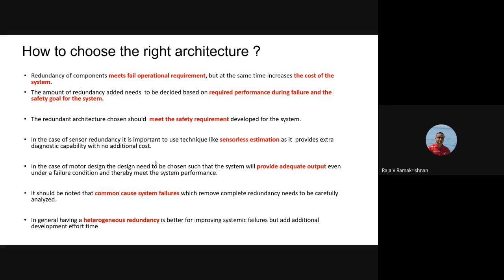You can have multiple windings there too, but you need to analyze such concepts and understand the common cause failure and bring down that FIT rate, making sure that by design also, motor failures are rare compared to sensor failures. So you need to understand that and take the risk and carefully analyze those areas.